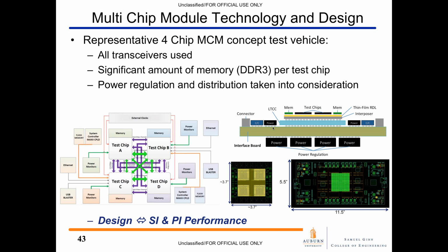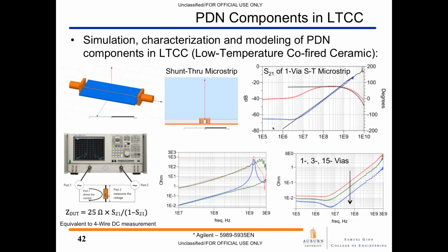CMP is, even with the newest 10 nanometer, 14 nanometer devices that are coming out in the next few years, the primary method because once you went to copper conductors, which all modern structures are pretty much using now as a conductor on the ICs, once you went to copper, there's no real easy way to dry etch them to get these small dimensions that they're at. And so the only way that I know of in the near future to planarize and to generate these very fine lines in copper is CMP. There's just no other way right now to do it.